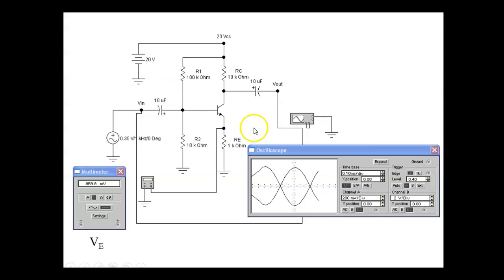Well, if the capacitor's short, it would measure 0. So that happens too. Capacitors can short, guys. So if I measure 0 volts there, or extremely low, then it could be the capacitor. It could be the capacitor leaking.